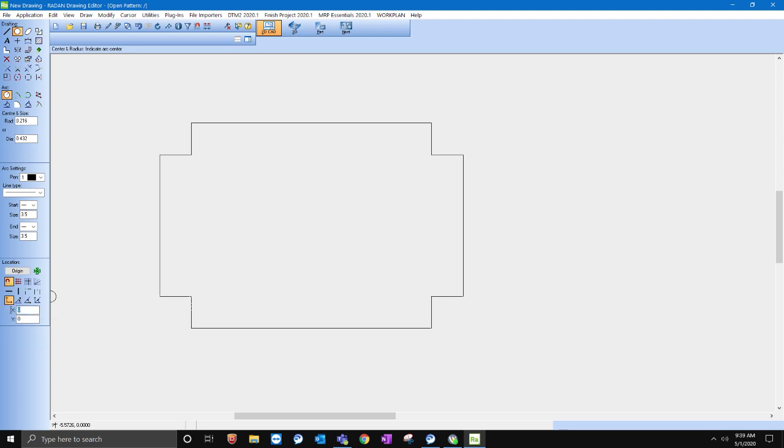So now I want to place a hole. I can come in here and go origin, select my origin point, and there's my new origin. Now I can come in here and go to enter X and Y coordinates, and let's grab a circle right here first, and let's go 0.375, actually, let's do 0.432 on the diameter. Right, enter my X coordinates. I'm going to go 1.0, enter, 1.0, enter. And there we go. I've put my hole in there, 1 inch in, right?